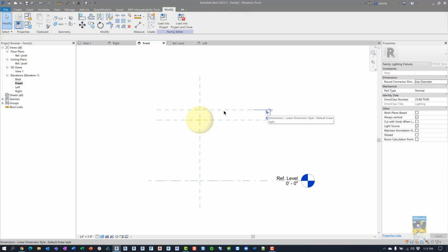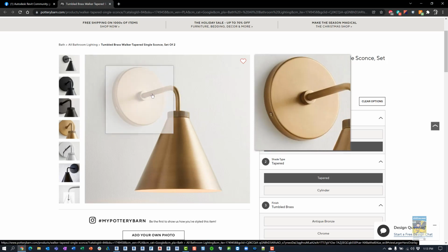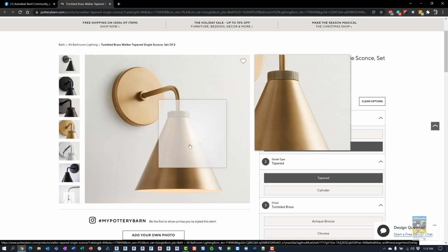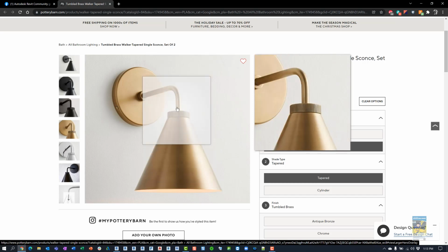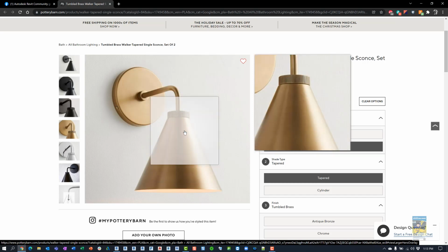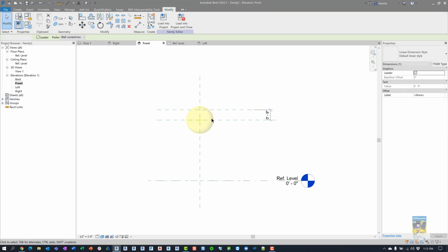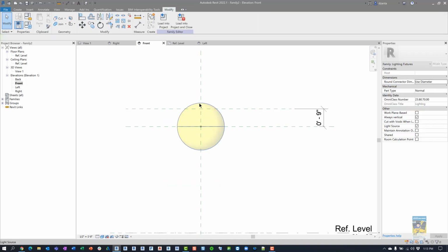Now we can parameterize this so that we can make the location of this base in relationship to this cone higher or lower, so that this part of the sweep gets longer, or we'll just leave it fixed for the sake of simplicity. So I'm going to keep it simple, take that 9 inches and lock it. That way that position holds. From there, I can create that extrusion for that base.